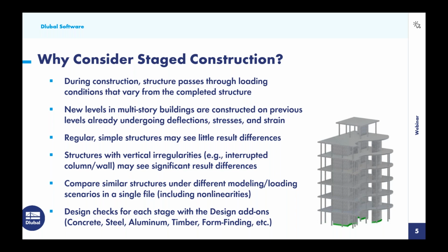And we also can include nonlinearities with these comparisons. So rather than creating multiple files with the first level completed, then the first level and the second level completed, we can consider all of that in a single model. Now, we also have the ability to run the design checks according to the various codes for each of these stages by incorporating them, again, with those additional design add-ons.